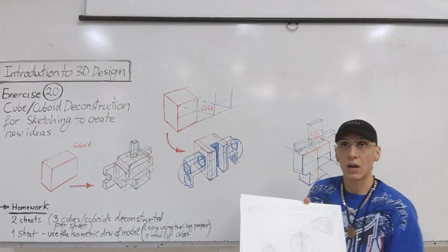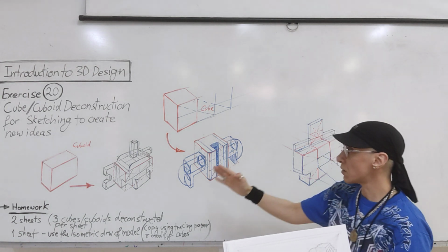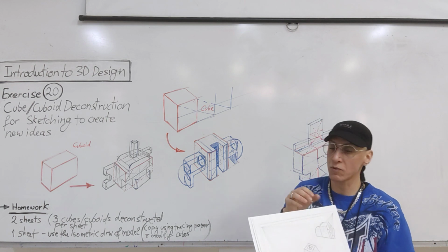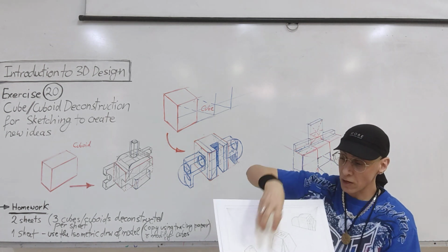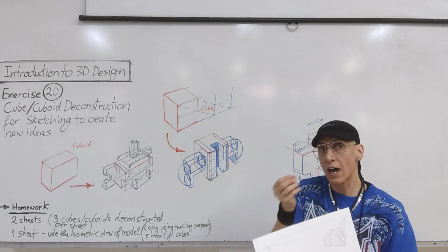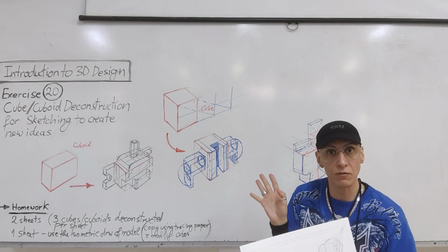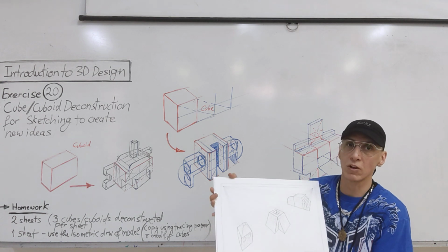Now, you will imagine some kind of an object that you want to draw, but this is the method of how you will start. You will never start with details. If you want to draw in perspective, you always start with cuboids, then start splitting, dividing, adding details, removing details, then adding any curved surfaces. So it's the same way. This is very important, okay?